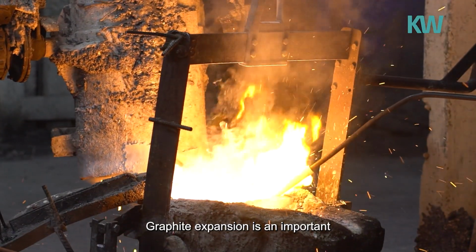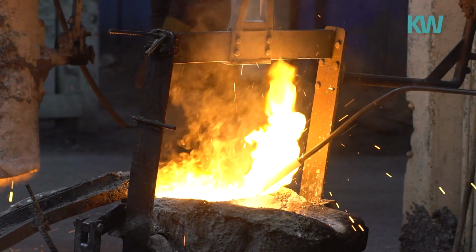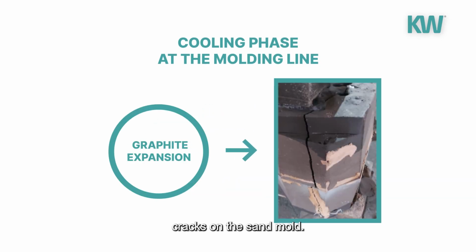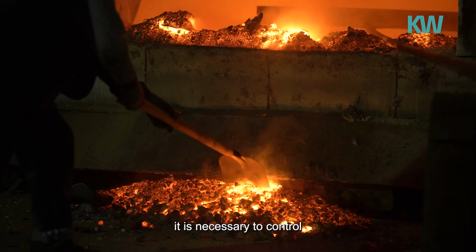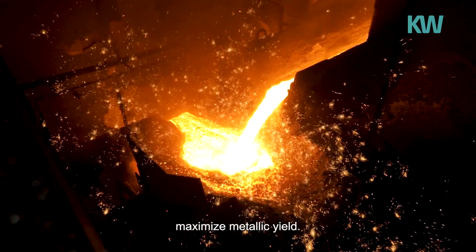Graphite expansion is an important aspect of the process to improve metallic yield, however, it has not received the attention it deserves. During the cooling phase at the molding line, the effects of graphite expansion become visually apparent due to the cracks on the sand mold. To overcome the shrinkage formation, it is necessary to control several factors in the melting and pouring process of iron, aiming to maximize metallic yield.